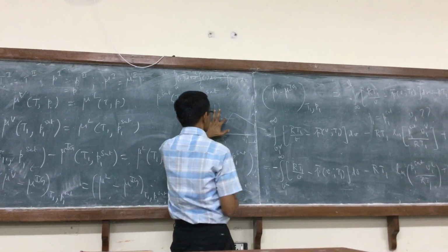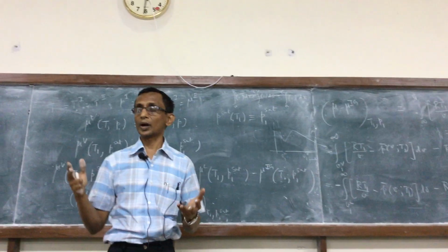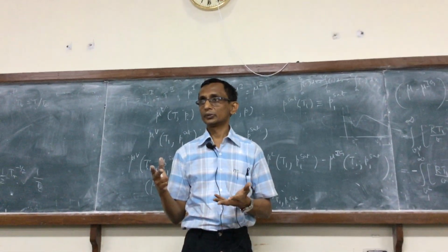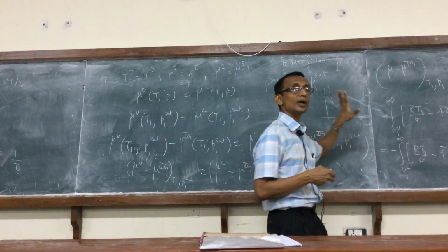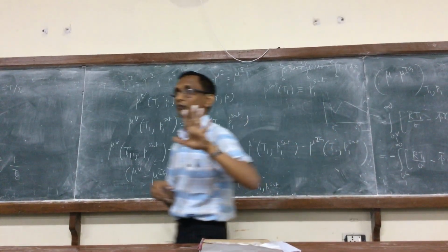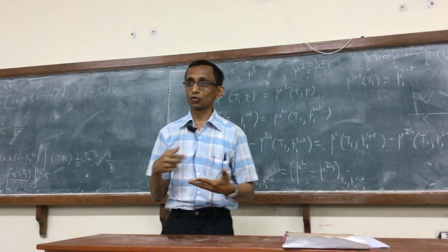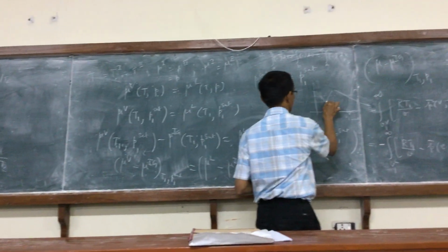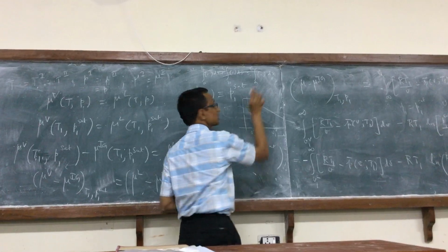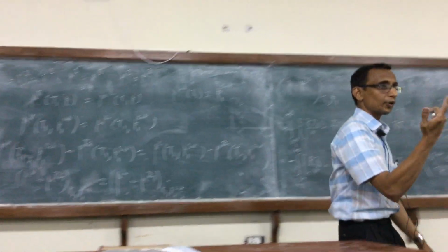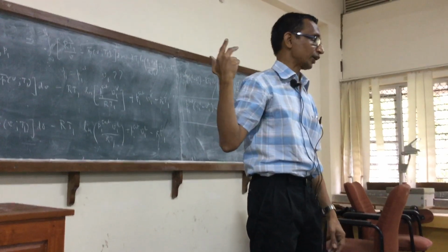The first step is, you write down the algorithm in great detail. First step is you have to assume a pressure, because you don't know, and you know that the pressure is between PA and PB. So immediately it would help if you calculate PA and PB first. Those are the pressures corresponding to the minimum and maximum. Because if I choose some pressure here, obviously I am going to get only one real root, as per the figure.